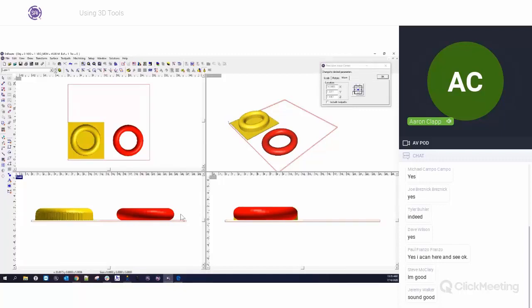Because remember, we're using 3-axis machines anyway. You guys are running CNC machines with Enroute that are 3-axis machines. So even if Enroute could create that object underneath there, Enroute would not be able to tool path it, or your machine wouldn't even be able to cut it, because your bit can't go underneath there unless you have a 5-axis machine.